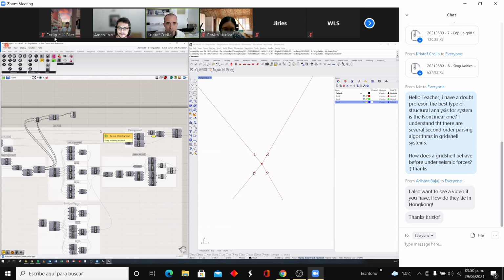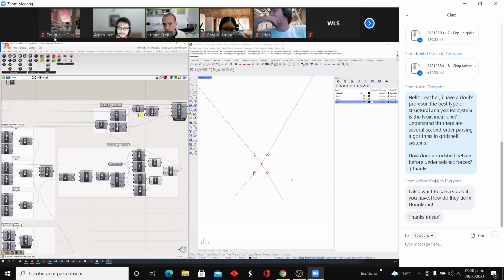So once I have this, I need to jump to my next point, right? So this live point is no longer live, it's taken care of. So that one needs to be removed from my point list. And the 4 original curves that I've joined need to be removed from my curve list. And the newly joined curves need to be added to it, right? So that's what I'm doing here.